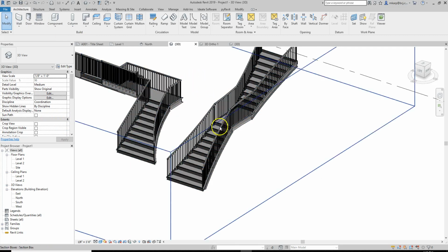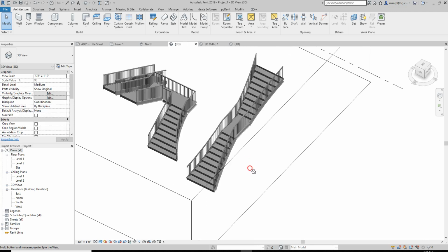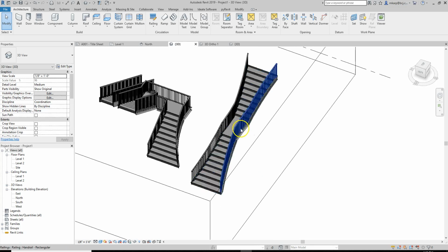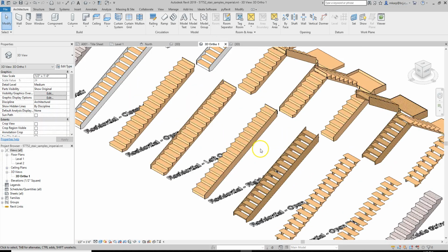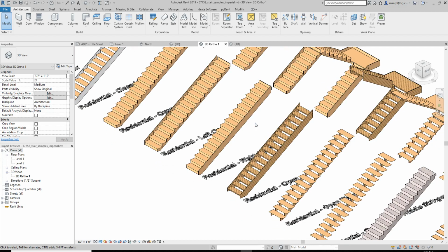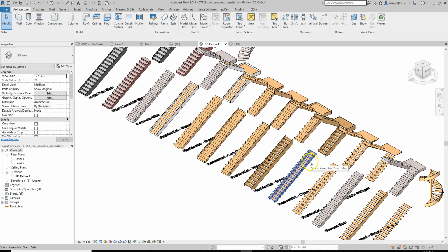Let's say that you don't like the defaults that come with Revit, but you might not know how to edit staircases very well, or railings. What you can do is you can actually download seed files of other staircases, even from Autodesk. Their knowledge base. You can download sample staircases and sample railings. And they look something like this. There would be a file filled with different staircases of different arrangements. And you can have all those settings. Now, they're not families that you can load in because they're system families.